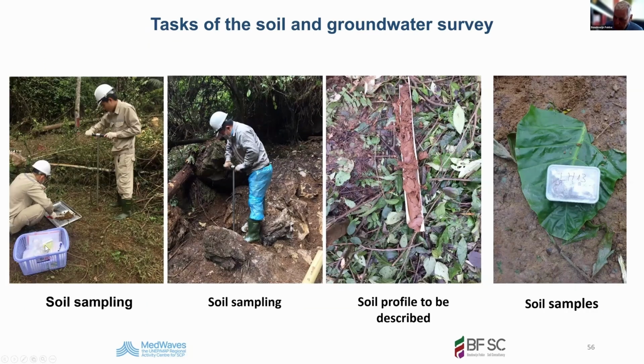Soil sampling, here a basket with, this is in Vietnam, a basket with my equipment and my bore logs and other forms. They used a tray to collect the soil cuttings and to describe and to take the samples. Here, gas mask, protective boots, trouser, and your sample should always be on a tray which is clean, or here this is a piece of a banana tree, and this was clean, so here the sample is. And this is my soil sample. The label on top here, LH13.